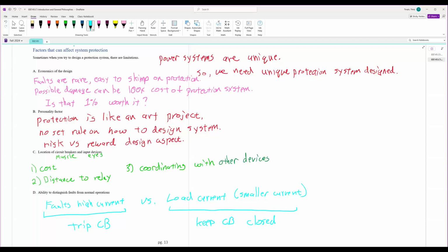And these regular conditions can also be a hot summer day, with everybody running AC. This could be a problem where we still need to make sure that we're massively loaded down, but we're not into this burned-equipment-down fault territory. So we need to make sure our relays don't operate. And there are plenty of times in history, especially in California, where it's extremely hot. We have a heat wave and protective devices have operated in the past and knocked out all of Los Angeles. So we want to design a system so that would never happen, okay?